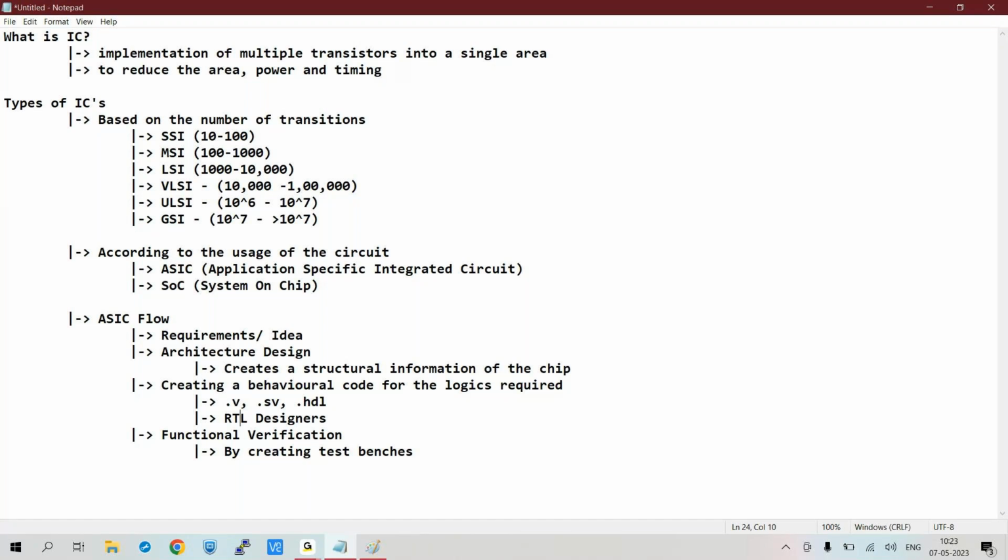No. No, right? So what I should do here is convert this behavioral code to gate-level information. That means this behavioral code present in the netlist, I should convert each and every logic to its equivalent SSI logic or MSI logic.